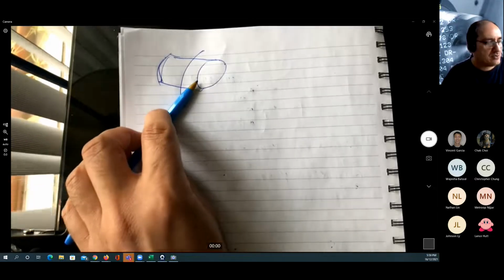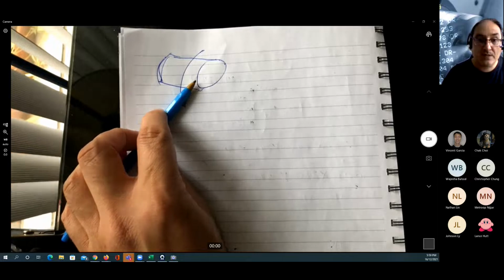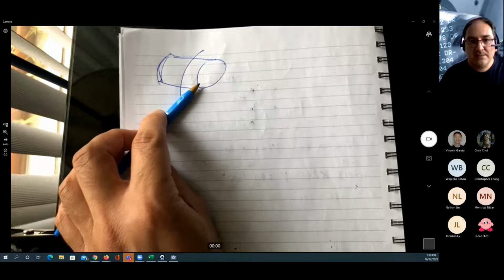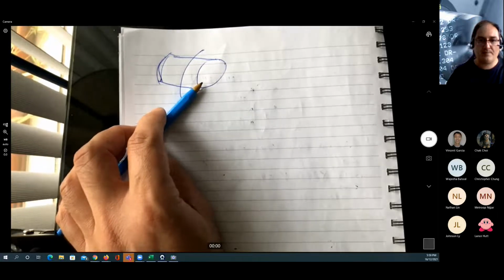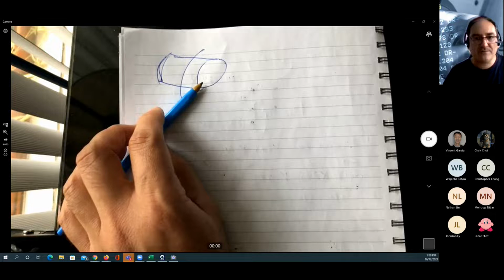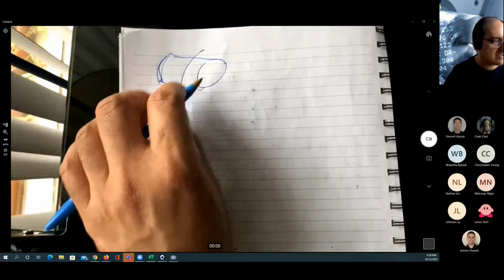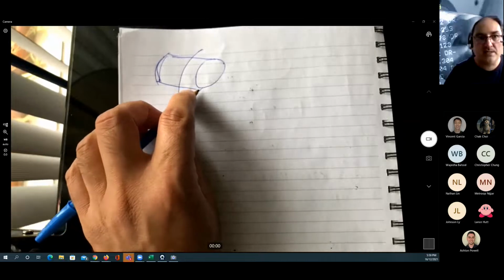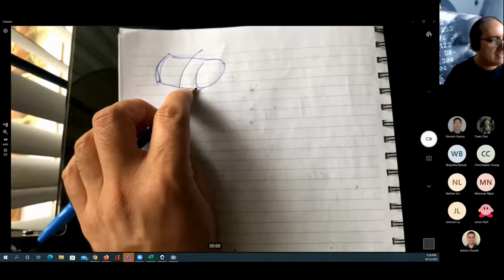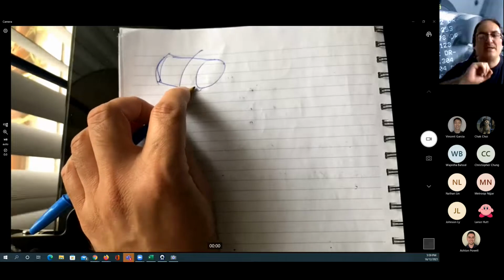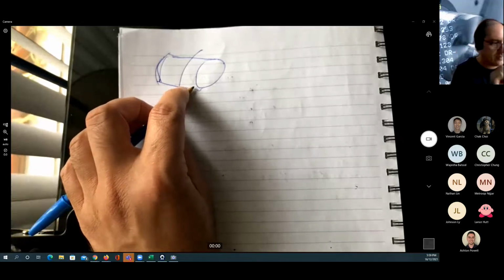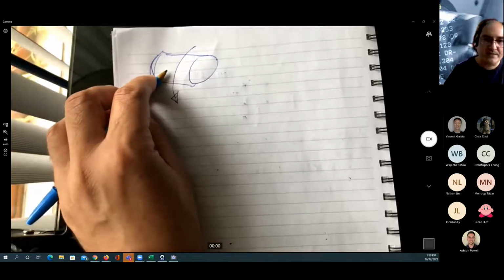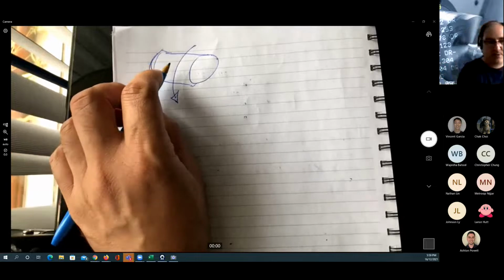And we are going to have the cutting tool coming in from one direction. Setting the depth of the cut, we are going to peel the part. Actually, we are peeling the part or shaving the part. Of course, it's going to be a single tip cutting tool, unlike the case of the milling operation. In contact, we are going to remove something like a thin wire away from one point. But as the cutting tool is moving in the direction of the feed rate, we're going to peel the whole part.